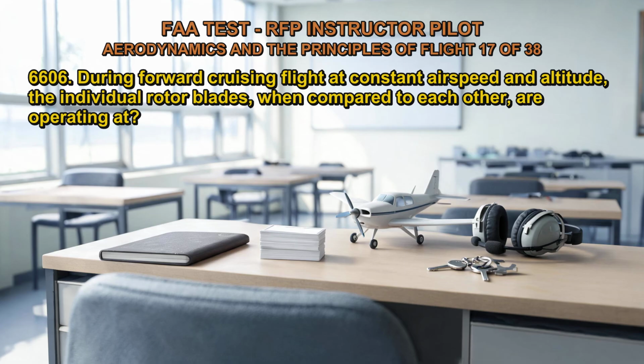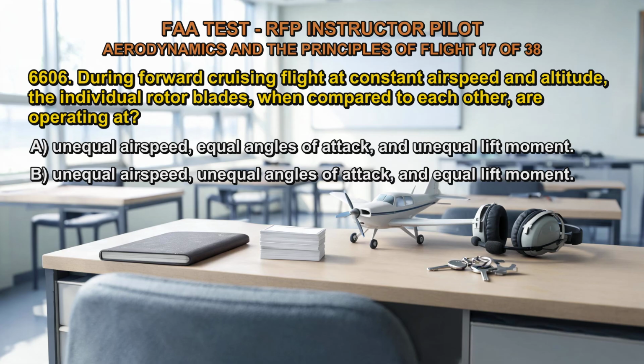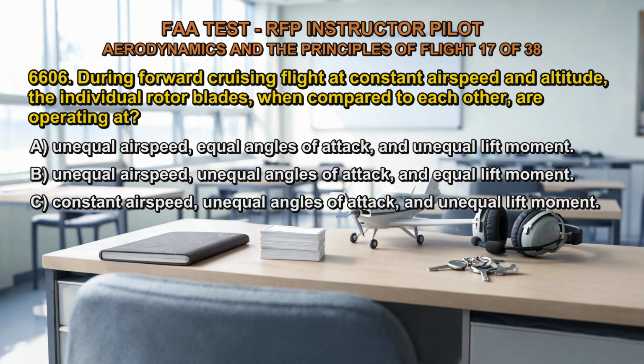6606. During forward cruising flight at constant airspeed and altitude, the individual rotor blades, when compared to each other, are operating at: A. Unequal airspeed, equal angles of attack, and unequal lift moment. B. Unequal airspeed, unequal angles of attack, and equal lift moment. C. Constant airspeed, unequal angles of attack, and unequal lift moment.